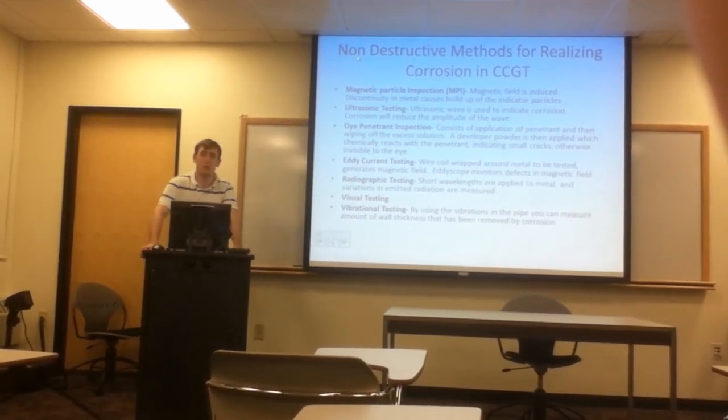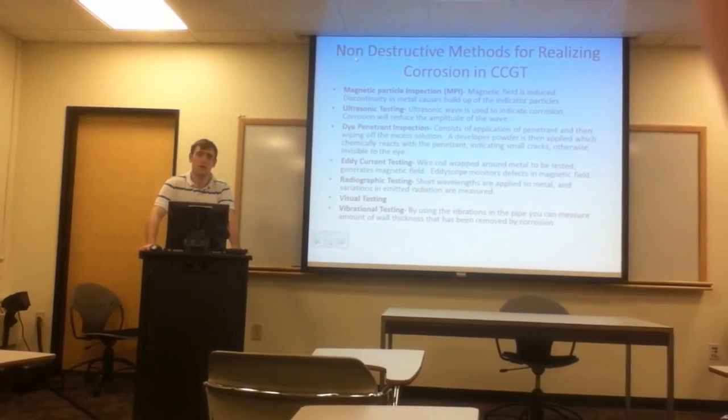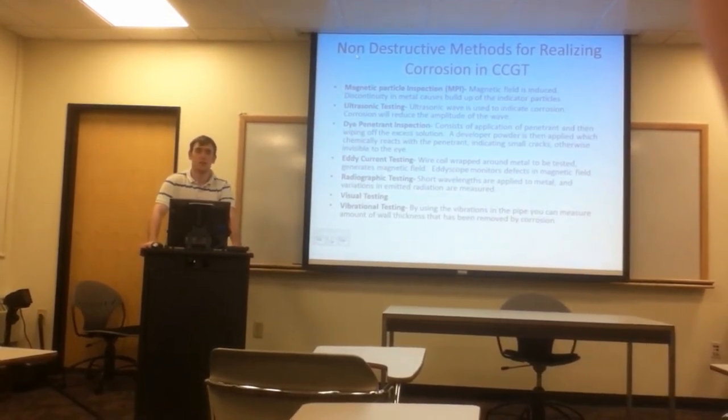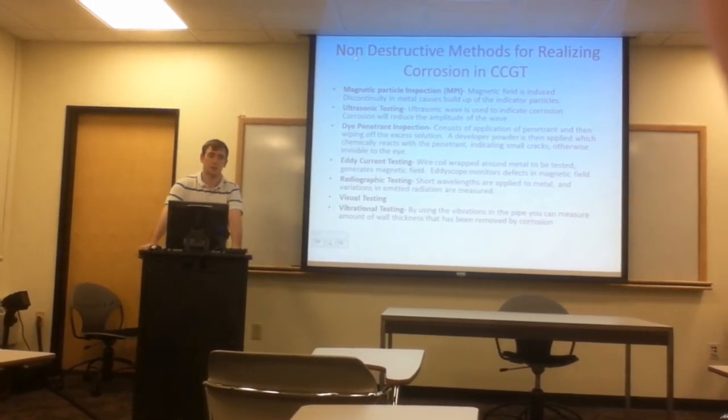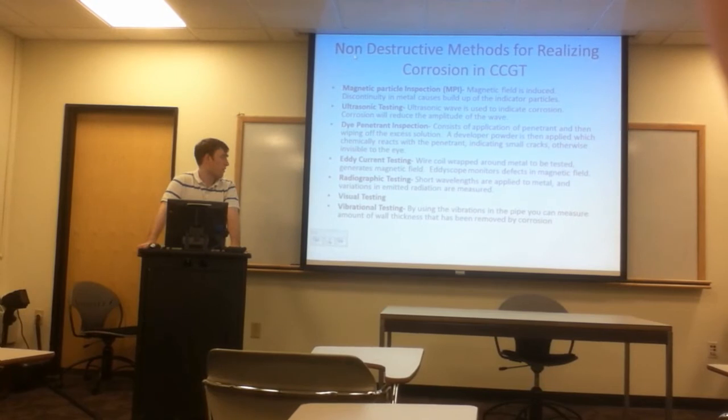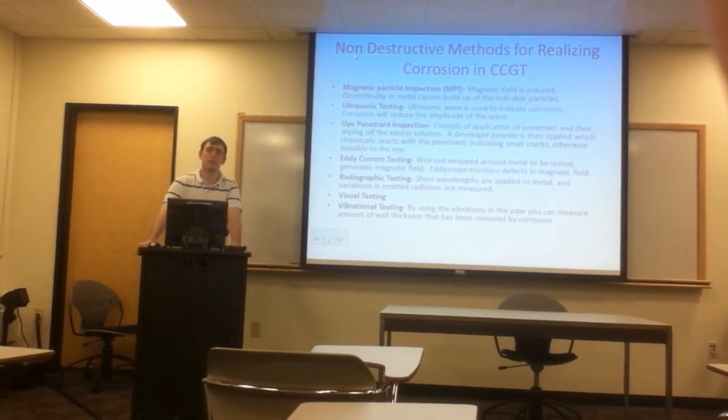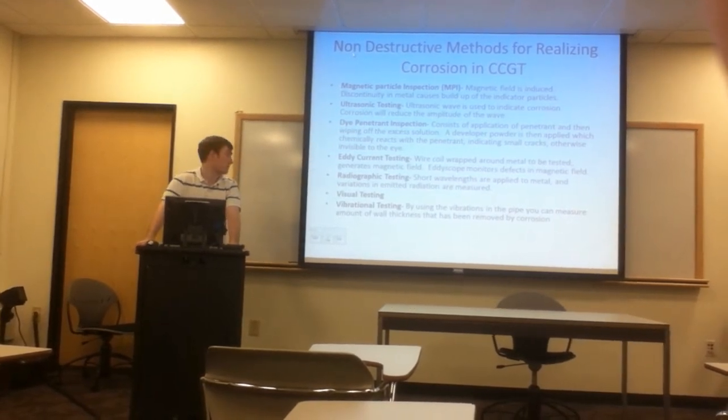Visual testing is also very important for turbine blades. Often you can see pitting, and you can see oxidation and hot corrosion. There's also a change in reflectivity of the blades as they corrode.